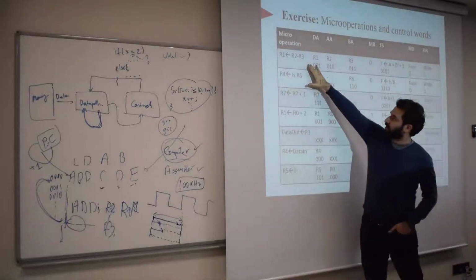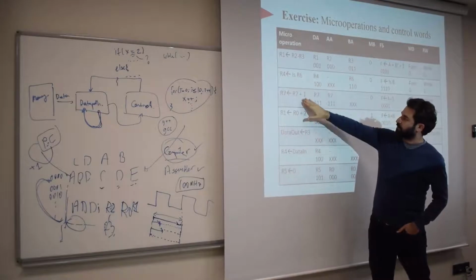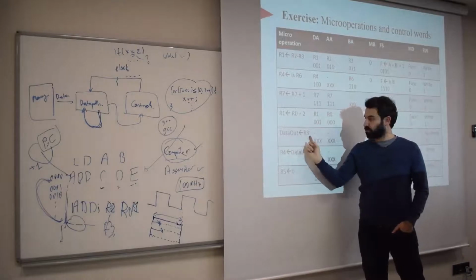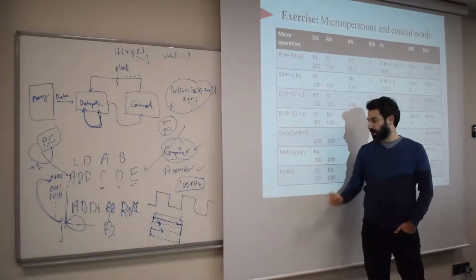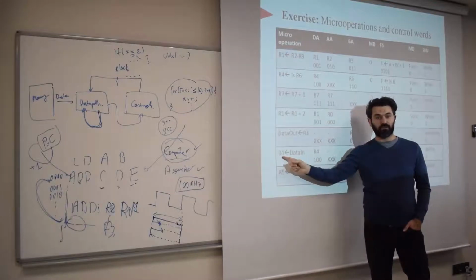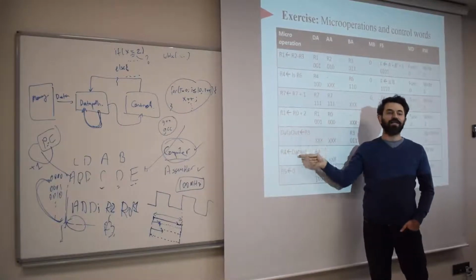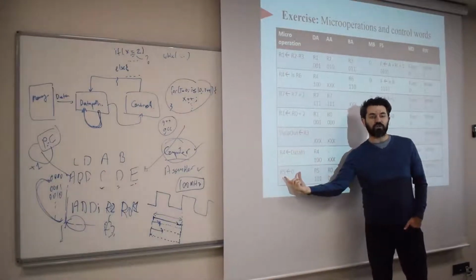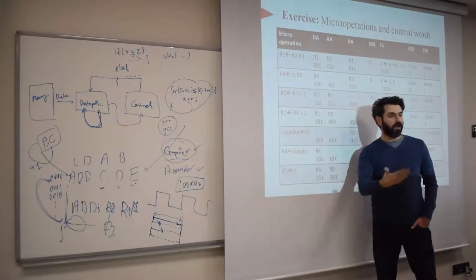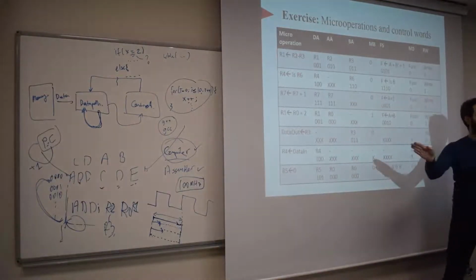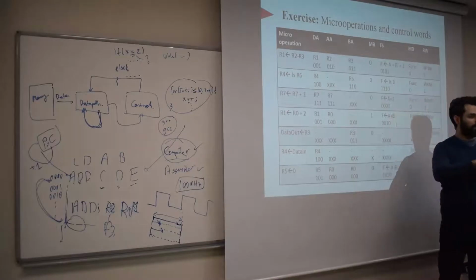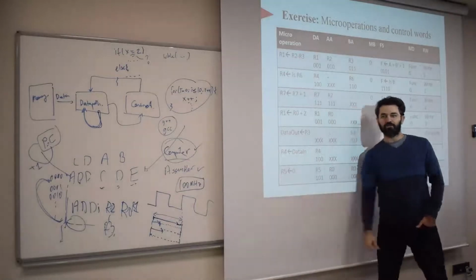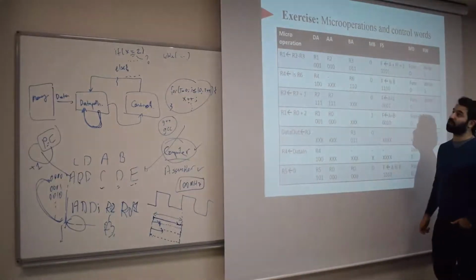So you have these 7 instructions. We have subtraction, left shift, 2 additions, and they're continuous. And this is very important because this enables us to transfer something to the memory, and this one is from memory to one of those registers. So these are like reading and writing from the memory, and zeroing out. This is also very crucial because before you start doing some operation, you have to zero out one of the registers, right? You want them to store some zeros so that you can operate on that. So one of the important instructions is just zeroing them out.